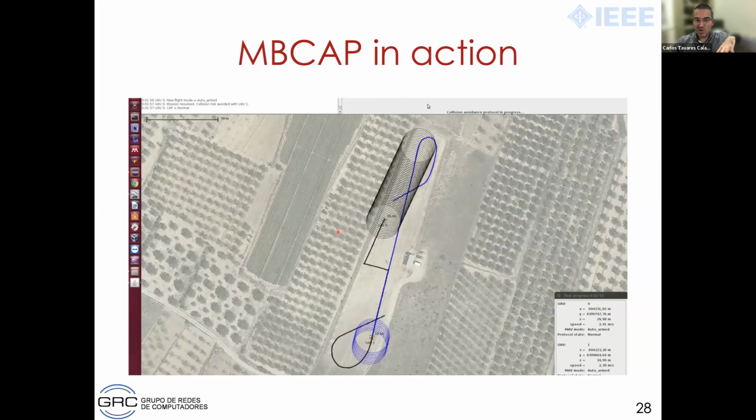Whatever protocol we are able to develop in ArduSim talks with the UAV using a MAVLink interface, which is a standard protocol for interacting with the flight controller. This means that once our code is working well in ArduSim, we just port it to real drones, and it also runs there correctly. So you have direct porting, because the emulation inside your PC is done very well, and this interaction is exactly like the interaction in a real drone. If you have a real-time response and everything goes well inside your server or PC, then you port to a Pixhawk based UAV. It cannot be a DJI or a closed controller. You must use an open source controller, and then it should be okay for this type of quick prototyping and testing. Thank you for the very detailed answer.